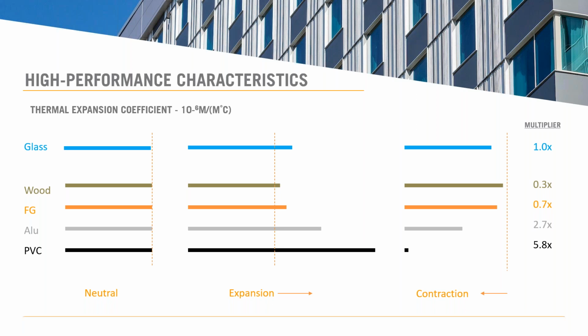There are seals in there, and different materials. So imagine the stress happening as those materials shrink and expand between all the joints and the seals, in particular between the glazing unit and the frame. If you've ever seen an old window with the seal popping out around the glass, that's likely to blame.